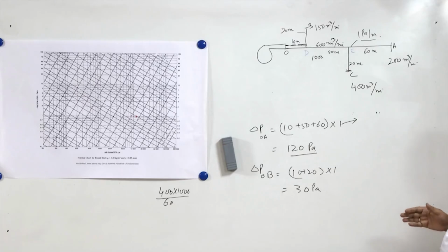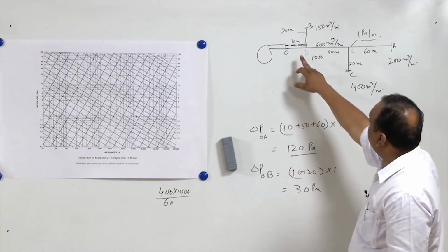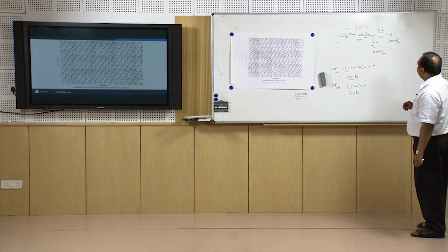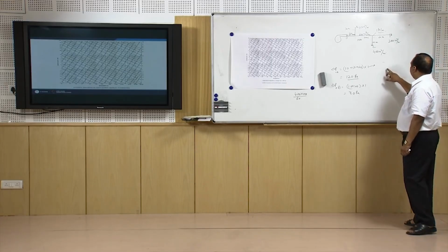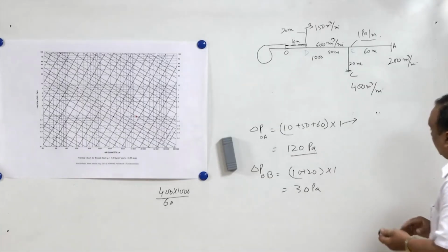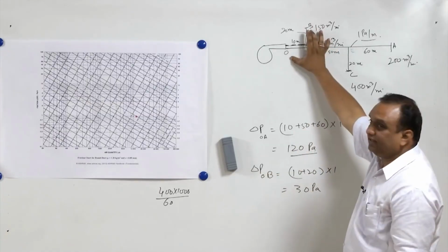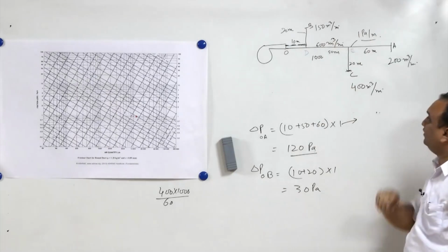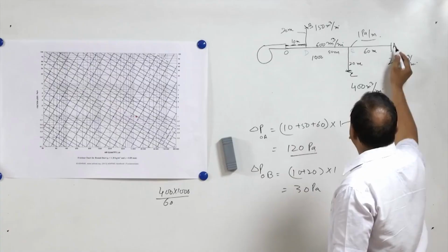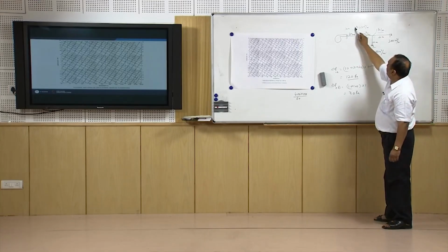Now in this case, what is going to happen? If we take pressure drop of 30 Pascal and the duct diameter, we already calculated. How much did we calculate the duct diameter here? 1150. No, dB we have not calculated. So if you look at the pressure drop between this and this, definitely pressure drop here is less, length is less, most of the air will try to leave at B, so we will have to provide dampers. So between this point and every outlet, the pressure drop has to remain constant. So this additional 90 Pascal will come through dampers.